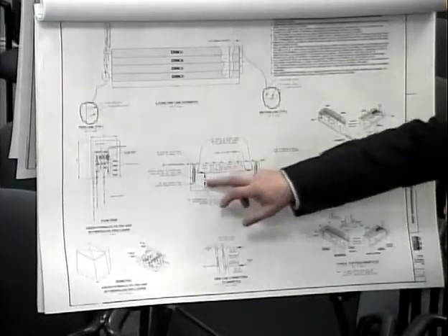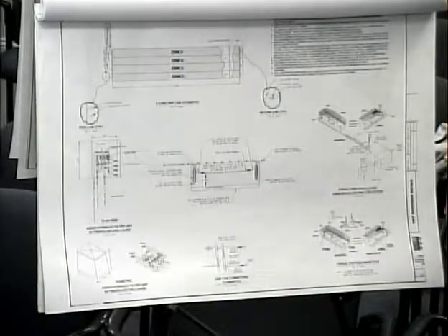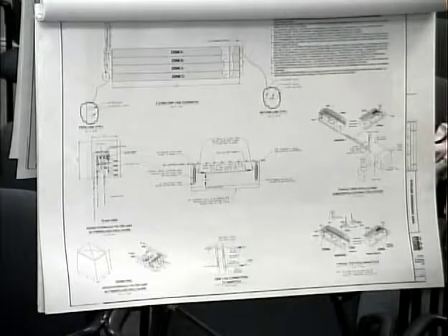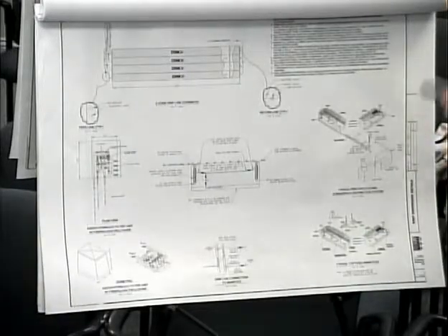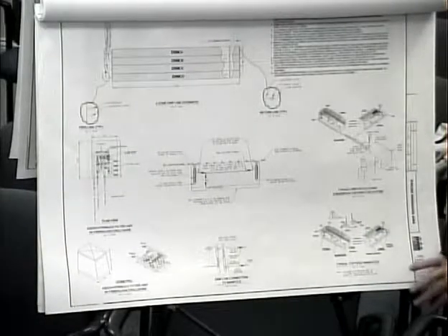Basically, it's just under the ground surface. Depending on which vendor you're using, some of them are set up with flow back, coming back to a station to drain the system so it doesn't freeze. Other ones don't have that, they have the emitters on the bottom and it just drains itself. These are dosed periodically and they're also flushed periodically.